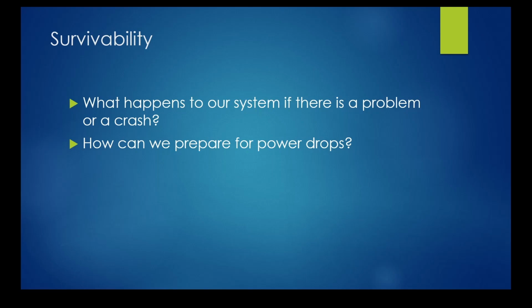Is there anything we can do to make the system resilient to power losses? Or will sudden power losses corrupt our system and render it useless? Let's refine this question. What happens if a power loss strikes in the middle of writing a file? Perhaps a reset occurred, the battery was depleted, or any other reason. We may now have a file that is in practice corrupted. What are the consequences to the system?